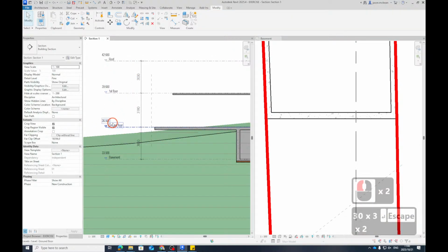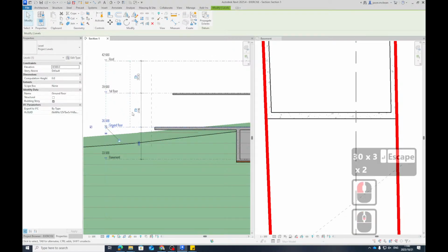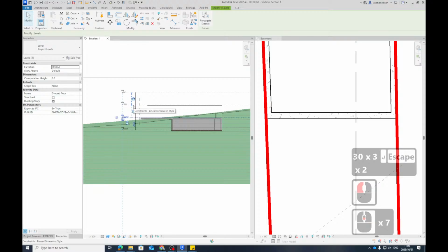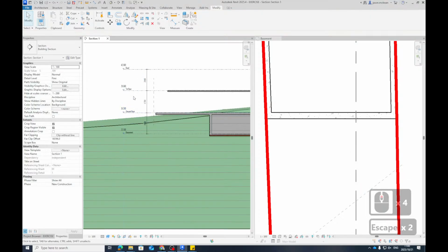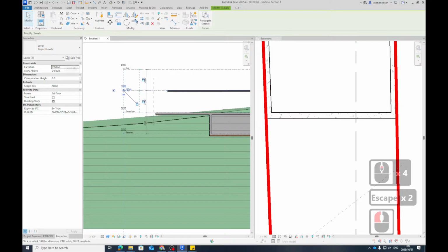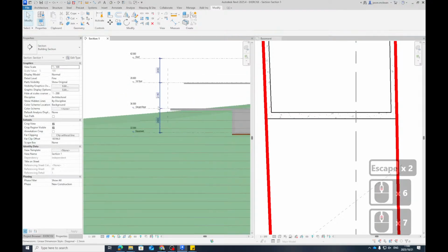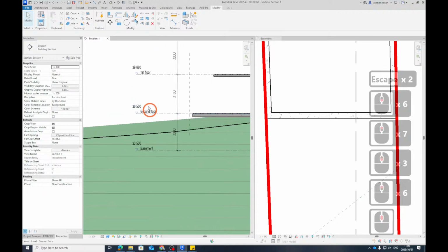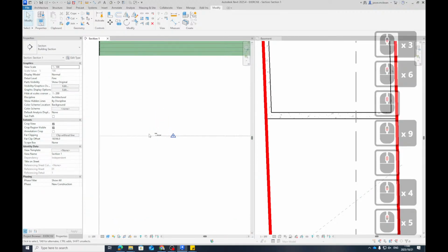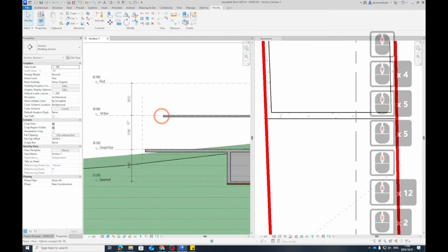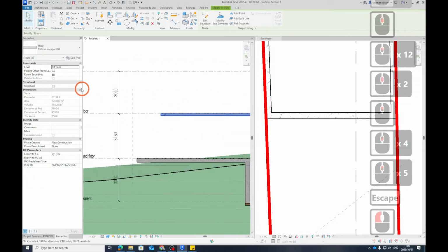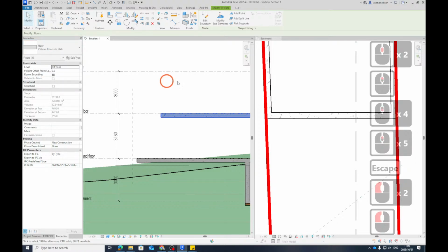What I've done is, you'll see that these are always referencing the sea level, so if you're working with a surveyor, we know that these are above sea level. But we can also use datum, so you need to decide, either we use a datum or we use sea level. I think sea level works fine. It just makes you understand what's going on more. You understand that this is above sea level. Typically, this is how we work with engineers as well. This is how we communicate. So this one will also be a 255 slab, by the way.